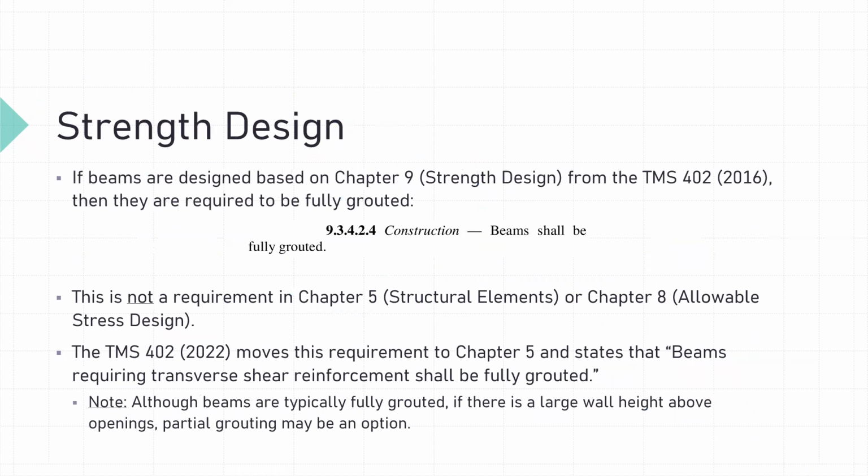If we design our beams or lintels with strength design, Chapter 9, we require that they are fully grouted. Section 9.3.4.2.4 says specifically beams shall be fully grouted if you use strength design. But I did want to note here, this is not a requirement in Chapter 5, which is our structural elements chapter, or in Chapter 8, which is our allowable stress design chapter.